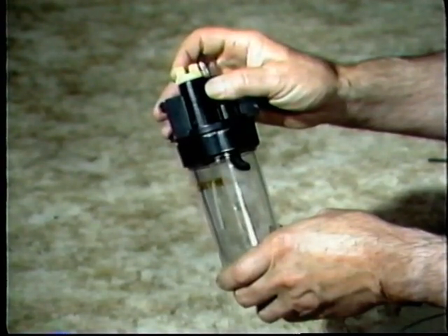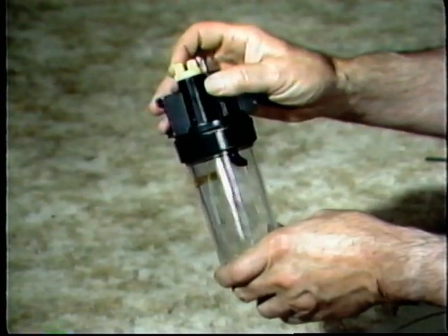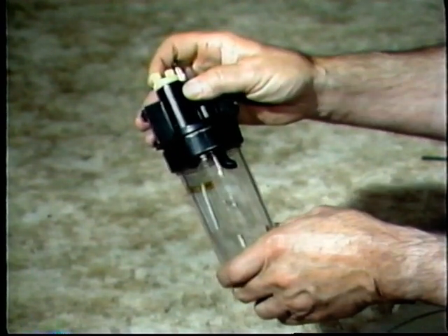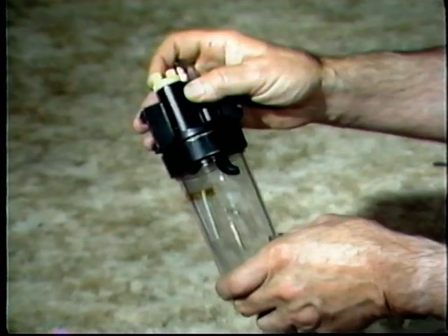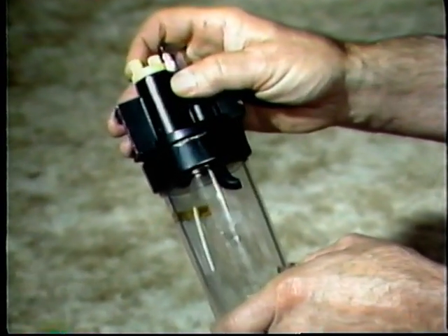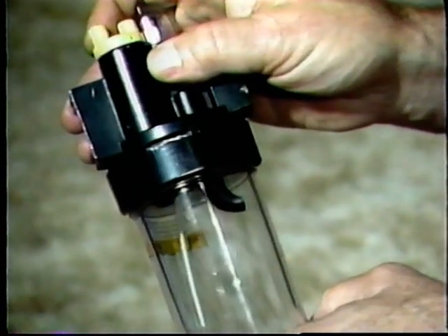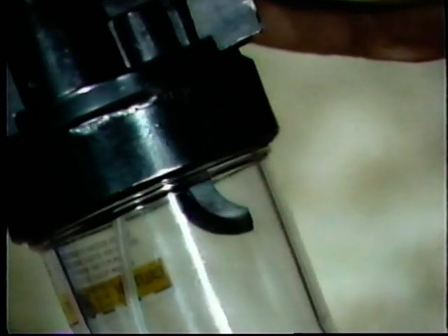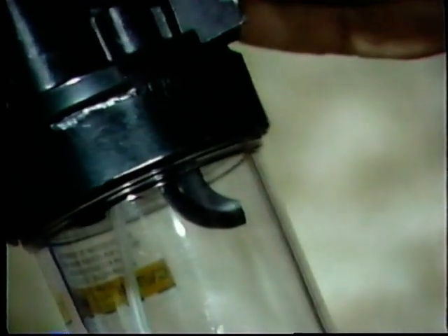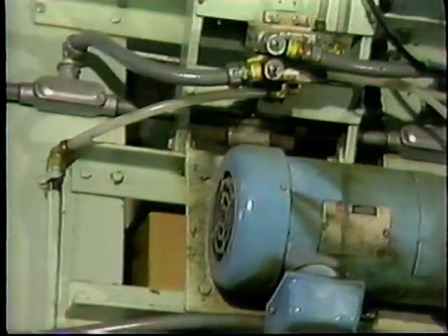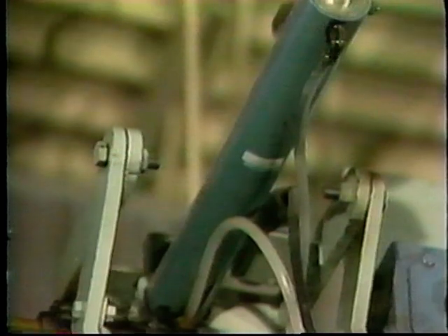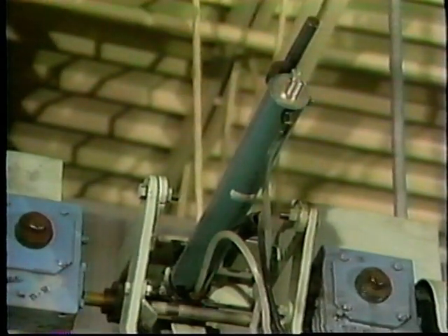When an extremely fine mist is required, a system may use this type of lubricator. It is called a recirculating mist lubricator. And you can see that on the outside, it doesn't look much different from the standard mist type we just covered. The big difference is that it can deliver oil particles ranging in size from 1/100th to 2 micrometers in diameter. One advantage of this kind of unit is that the smaller droplets will stay in suspension over a greater distance or for a longer time, so you can have a longer run from the lubricator to the work point.